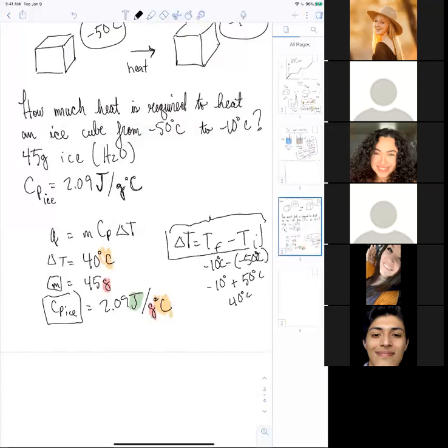So take T sub F, whatever your final temperature is, and subtract your initial temperature and plug that in. And whatever the sign change on that is, is the appropriate sign. You don't arbitrarily just assign a sign to the temperature, right? It's guided by this equation of taking the final minus the initial. And I might be wrong that it's always positive, but that doesn't really matter.